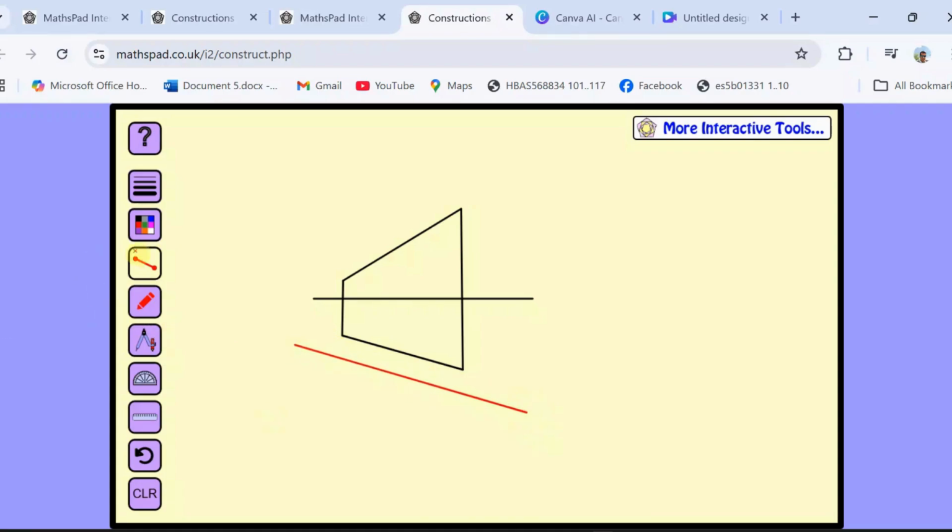And then in the third step, we draw projection lines from the points to the reference line. Although I have drawn a freehand sketch, let's assume these projection lines are perpendicular to the reference line, and the reference line is parallel to AB. Now we should measure this height, let's say h1, and this height, s2. We should transfer this h1 and s2 from here.